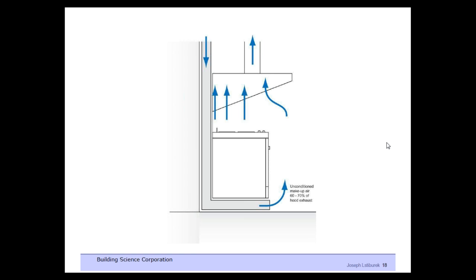You have to have a hood that's wider than the cooking surface and deeper than the cooking surface. You know how to do this from the experience in restaurants. What we are in essence doing is simply downsizing the standard practices in a well-designed commercial kitchen. Next.